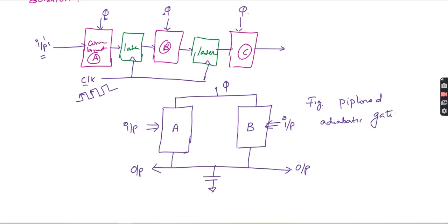Because here, see, this will be your load capacitance. Okay, so here the load capacitance may be charged through one function network, either through this network or through this network. It may charge, but discharge through another network. The load capacitor may be charged through one function network A, maybe this.